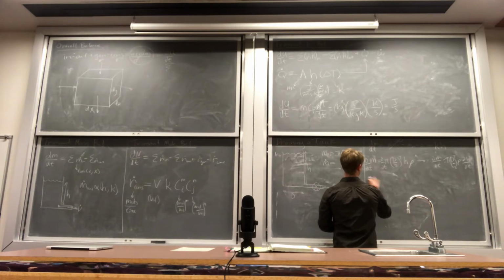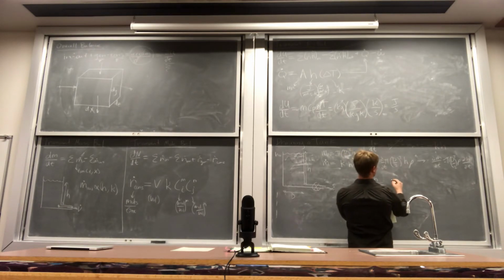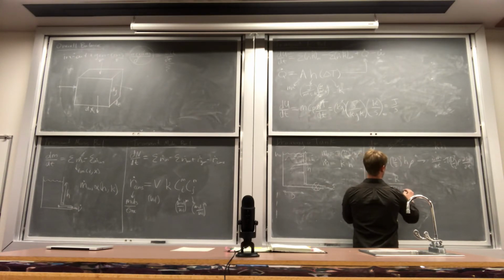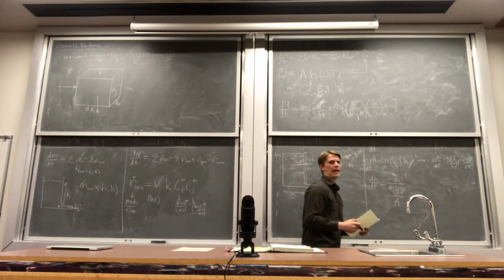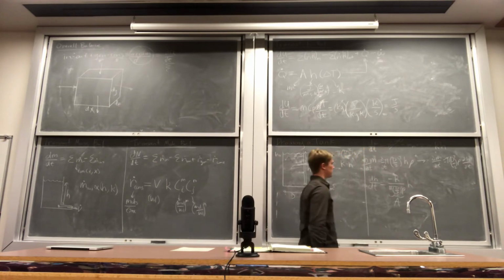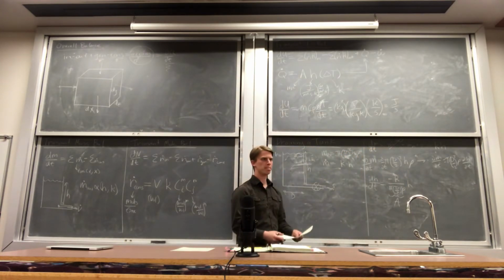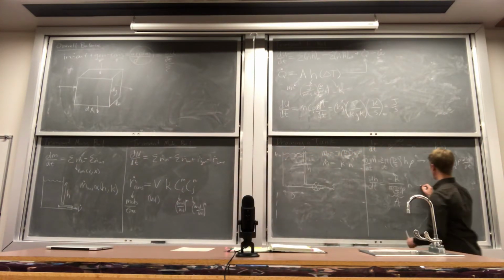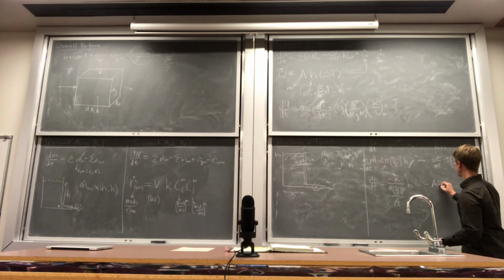dH, it's a total differential, not the partial. dH dt is equal to minus k over pi d over 2 squared times rho. I'm going to call that A to make it simple on my math, and times H. So to rewrite that, this will be minus AH.